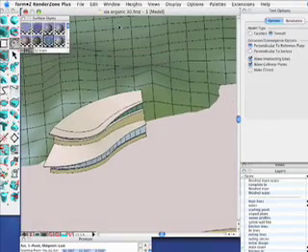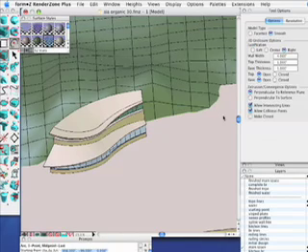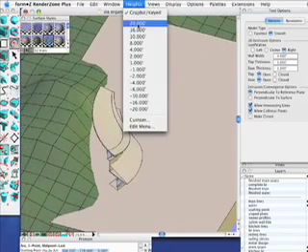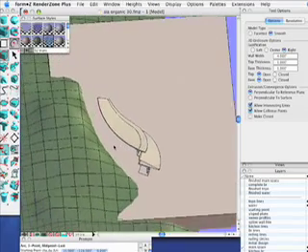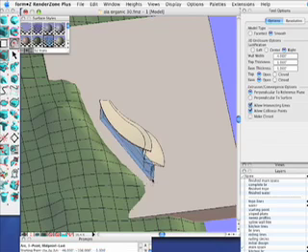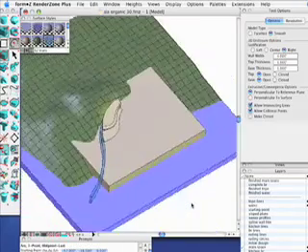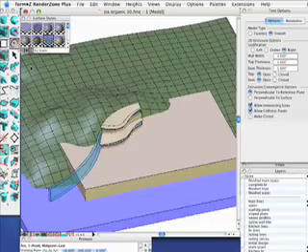Alright, how about a back wall? Let me set an arc tool, and I'll use glass as my color for this, just for the sake of demonstration. And I'm going to do an offset. I've set a wall width of 4 feet, and I'll preset a height of 20 feet, so you'll see how it looks as I'm drawing it. I'll just set the points of my arc, and I'll actually do a compound arc here. Make a little kind of an S shape.